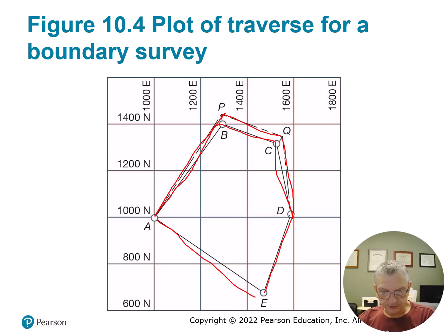So also in section 10.12, coordinate computations and boundary surveys, I'm basically just going to go back to that previous illustration where they call it radial traversing, but we're going to observe other points from our traverse than just the next traverse point. You're not going to have just one foresight at each total station setup unless you're doing a large boundary through the woods where there's just nothing else to locate.